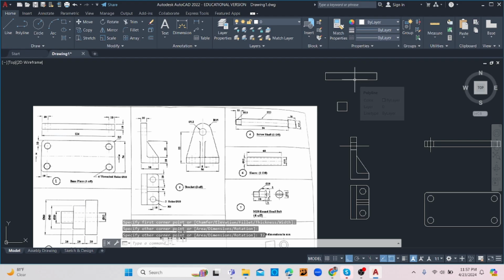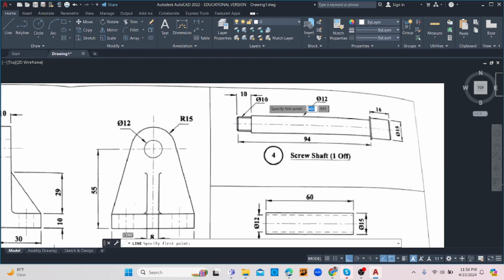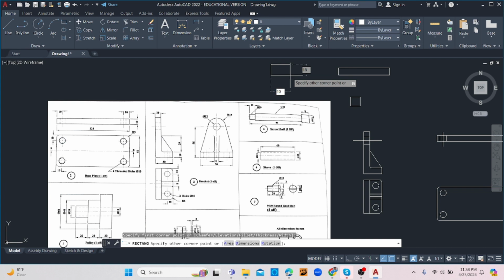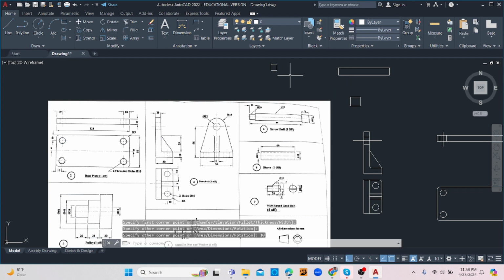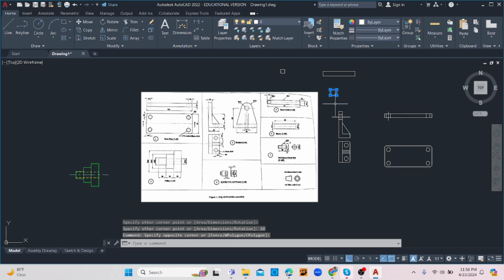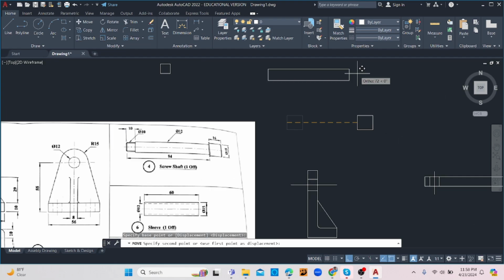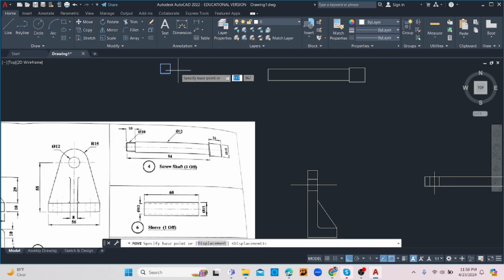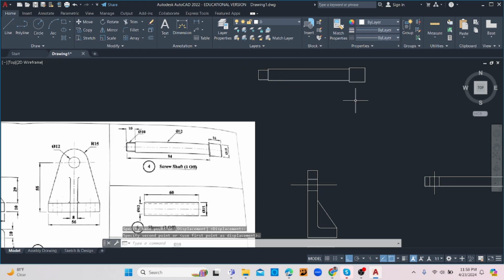Alright, once that is in place, we can now draw this rectangle here, which is going to be, they say that the diameter is 10, so you know it's going to be 10 by 10. So let's draw that one there. So it's rectangle, 10, tab key, 10. Let's now put them together. So this will now be where, let's move it from here to here, ensuring that I'm selecting suitable base points. Move this from here to here, almost there.